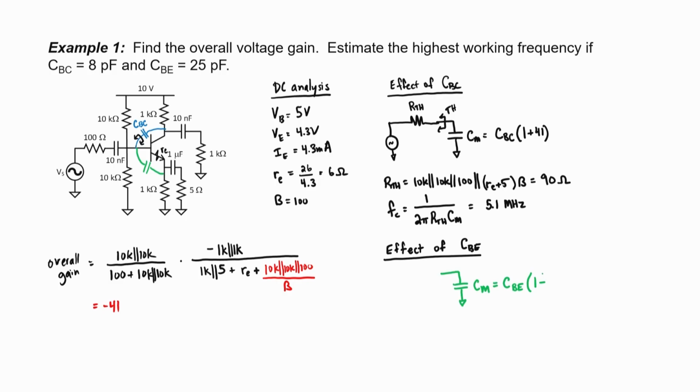But what's the gain of a common collector amplifier? You see, it's non-inverting. The signal here is pretty much the same as the signal here. They're 0.7 volts apart, and the little R sub E makes a small difference, but basically it's a non-inverting amplifier with a gain of about 1. So this number here is nearly equal to 1. The Miller capacitance can be approximated here as 0. Basically, the capacitance becomes so small that we don't have to worry about it at all.